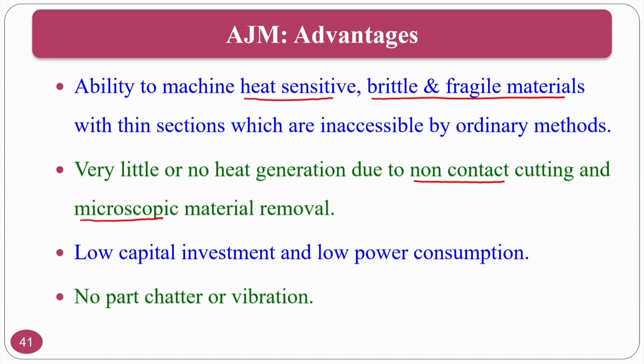What you have to do is firmly hold your workpiece so that if there are any small, minute chatter effects, they can be avoided. The machine can machine very hard materials, that is, hard and brittle materials. Normally brittle materials are hard materials also, so you can do the machining of these hard materials.